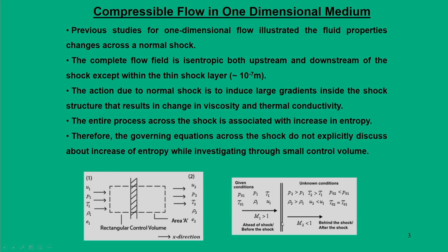In this thin region the flow is also a process that increases the entropy. Even though the flow field outside is isentropic, within this region the flow is non-isentropic, and in fact, we have proved that entropy always increases across a normal shock.